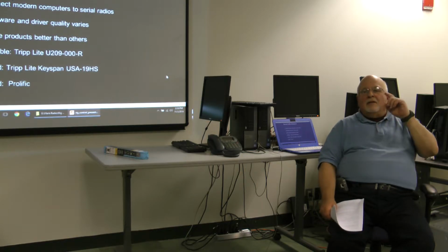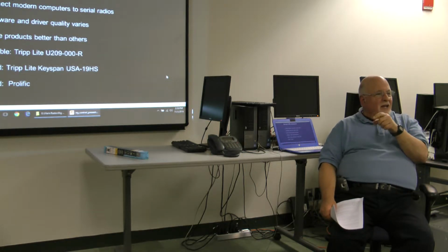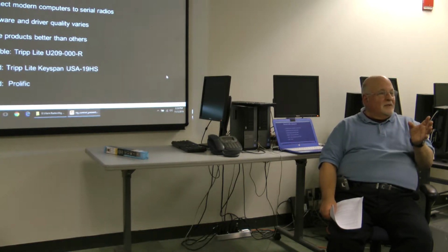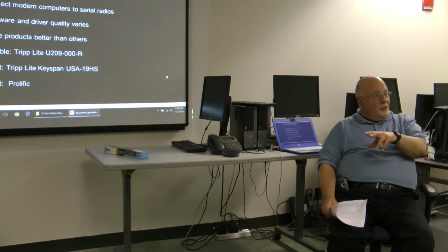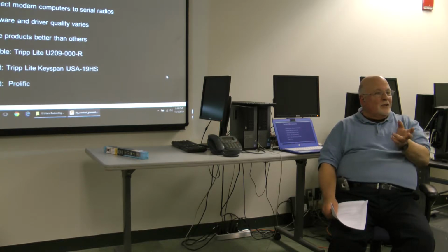If you go to the Miklor site, MIKLOR, who are the experts on the Chinese radios, they have up on their site the old Prolific driver that works with the counterfeit chips. But the problem is, every time Windows does an update to the Prolific driver, it installs the new driver, which doesn't work with the old chip.